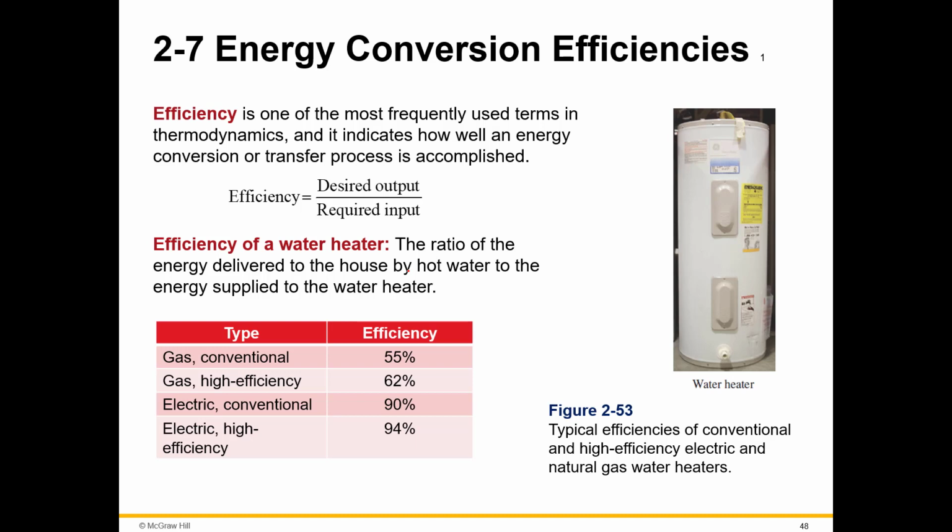So one of the projects that I usually do is to measure the efficiency of your air conditioner. And maybe when you hear that, you think, oh my gosh, that seems like an ordeal, like a big project. But really, you're just measuring the desired output and then the required input. And so it's really just two individual temperature readings that you can plug in there.